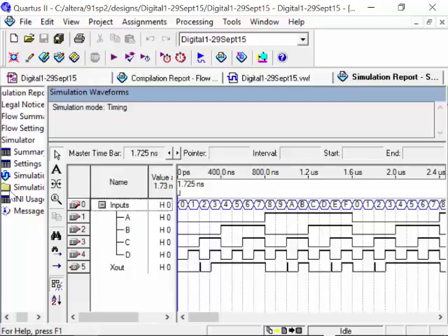That there. So, okay, well, as I said, it was going to be relatively short. It wasn't that short, but by the time we went through everything. But that's the whole process of implementing a design in Quartus and putting it onto the hardware and testing, verifying. We put it in the design. We just drew the schematic. We compiled it. We simulated it. We assigned our pins. We programmed the part, and then we tested the part on the board.